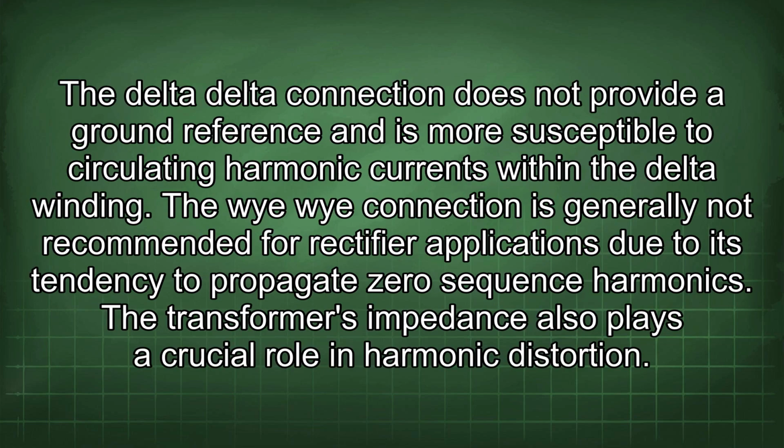The delta-delta connection does not provide a ground reference and is more susceptible to circulating harmonic currents within the delta winding. The YY connection is generally not recommended for rectifier applications due to its tendency to propagate zero-sequence harmonics.